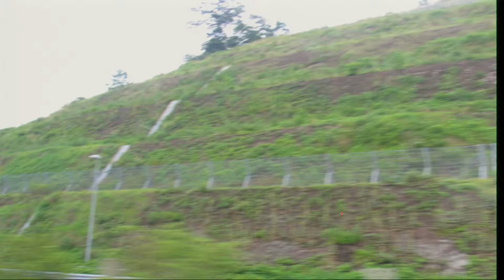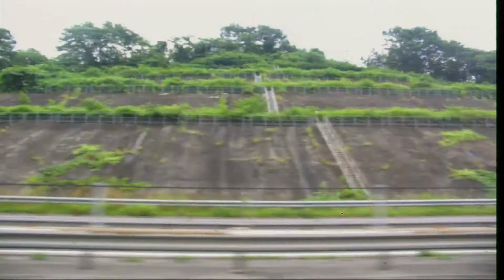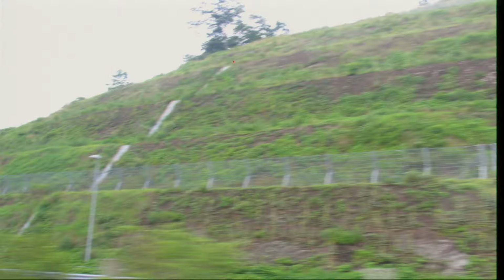There is an example from Japan. I may have a better photograph, maybe this one. You have the drain which is coming down here, and then they have cut the slope in different benches. So, they have reduced the slope here and tried to stabilize it, and in some places they have also put fences or wire mesh so that if some block rolls down, it will be blocked here.